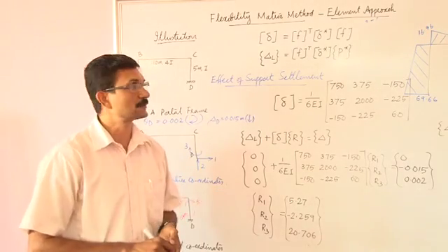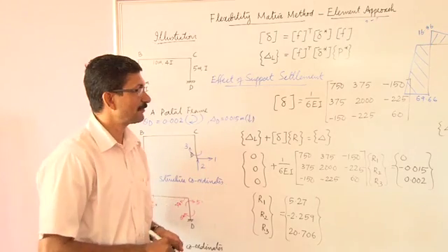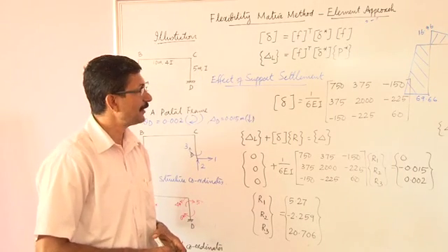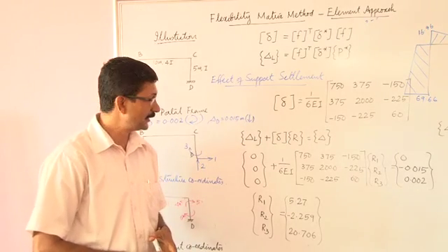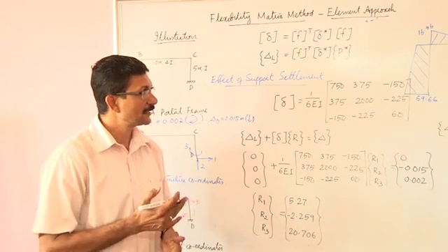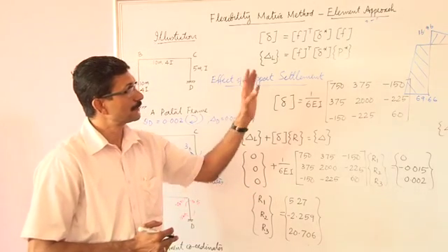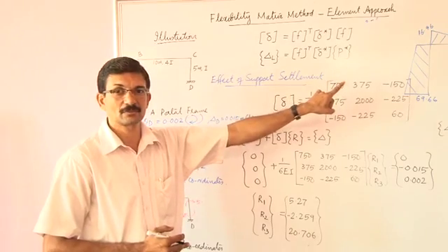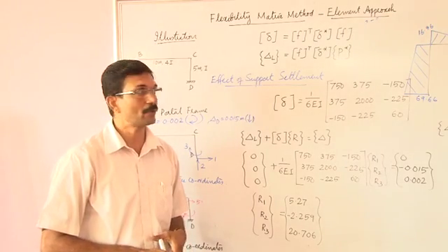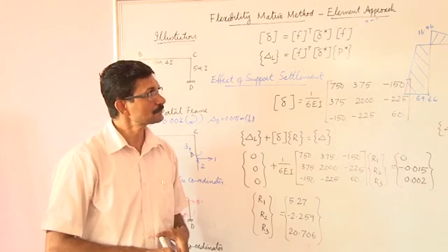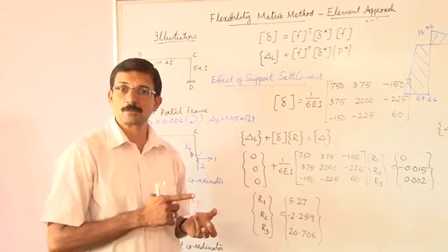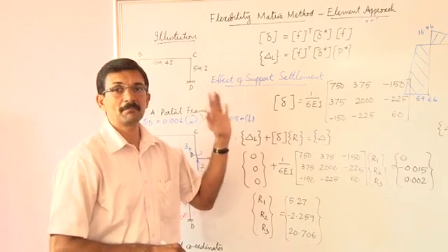In case of pin jointed frames, say plane trusses or even space trusses, we can find the axial forces in all the members. So that is the matrix approach, which is a convenient way of analyzing structures when the degree of static indeterminacy is lesser than the degree of kinematic indeterminacy. But we can see that the degree of static indeterminacy of rigid jointed frames, when you go to the higher end, when you go for a multi-storied building frame, DS will be much higher than the degrees of freedom or degree of kinematic indeterminacy. In such cases, it is better to go for a displacement based method, which is going to be discussed next: first the slope deflection method, and further the stiffness matrix method.